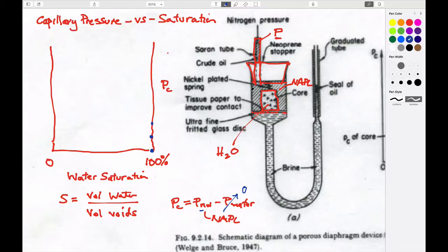In the next step, all of a sudden, when we put it up to the next pressure here, it allows a small slither of this other fluid to go into it, then by definition the blue phase has some small saturation and the water phase has somewhat less than 100% now, which is this amount here. So this would be our new equilibrium point.